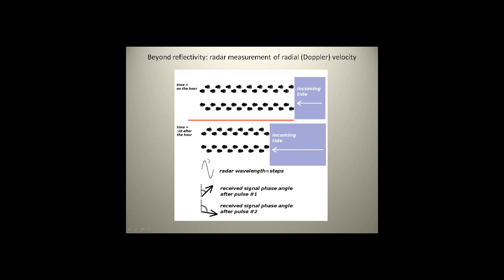So when we're trying to make this measurement with a Doppler radar, we replace our carefully equal steps by knowing that we're sending nice steady wavelength pulses from the radar. So the trip that the radar pulse makes out to the target and comes back, you can think of as a distance of travel that amounts to so many wavelengths in terms of progressing through space by the radar signal. We don't really care how many steps it takes to get out. You just knew that the number changed by 4 steps between your 2 measurements.